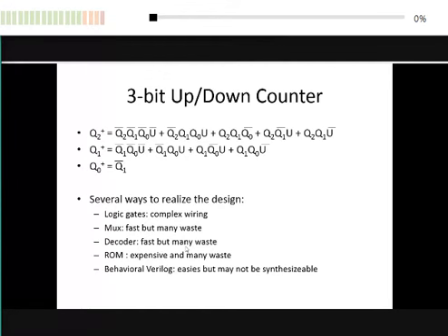Okay. But in multiplexer and decoder implementation, there are many ways. Because even though unused internal minterm is there already, you don't use. But sometimes, like I said earlier, when we want to build a finite state machine, the most important thing to consider is whether this is the first prototype. If it is the first prototype, time is the most important thing. So use multiplexer and decoder. You can use this technique when you build your group assignment later on.